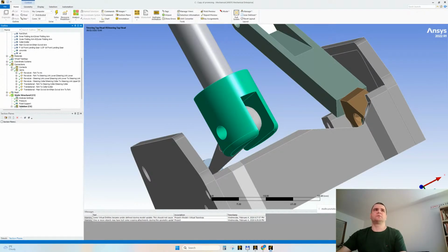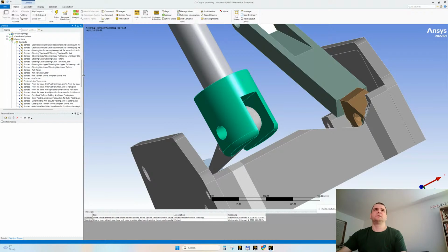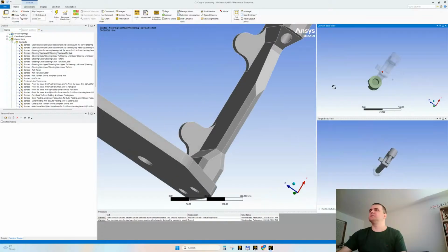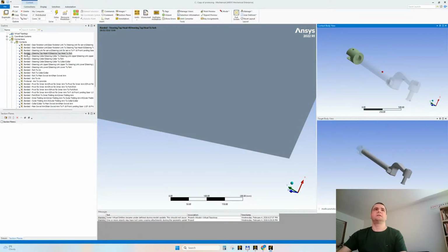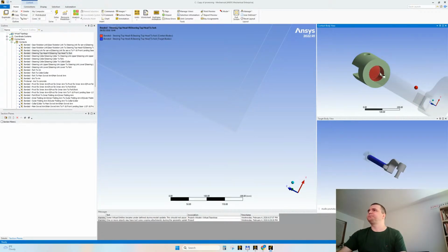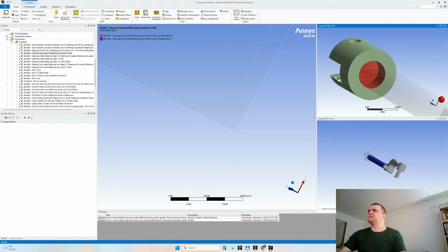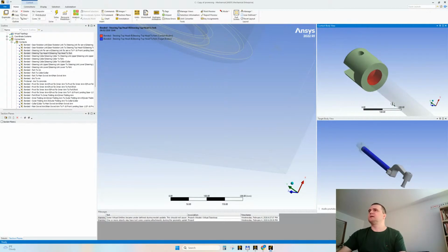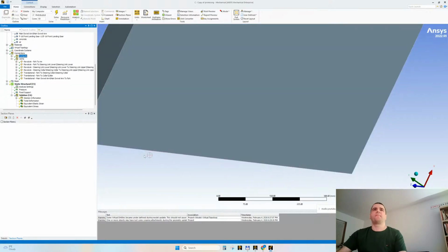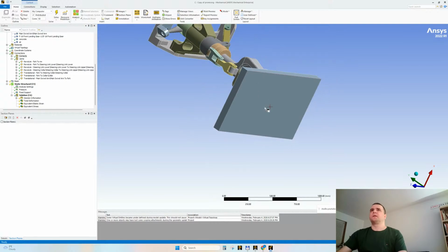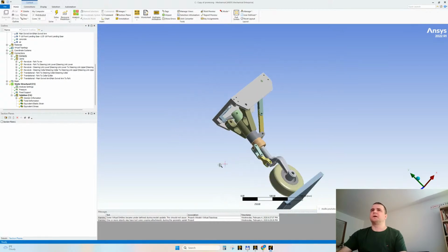I will look here on the contacts and remember about steering top head and the fork. Yeah, this is the contact between the two. Let me unsuppress this because this should be bonded here. Yes, maybe it is threaded, is screwed in. Maybe the shaft is screwed in. Maybe we don't know at this moment. So let's have that contact there. I was here. All right.